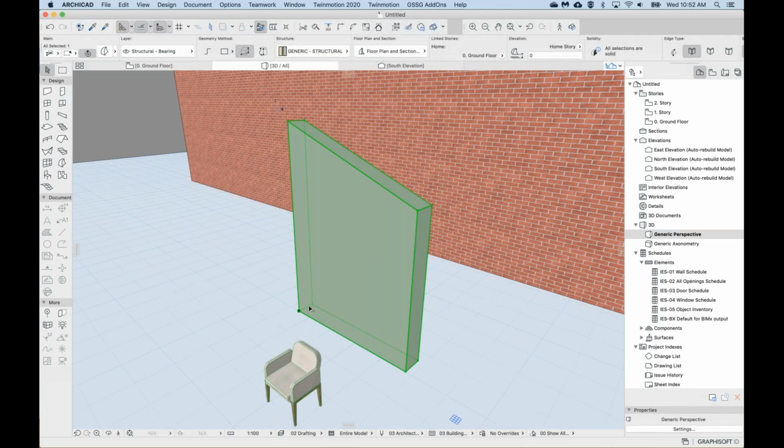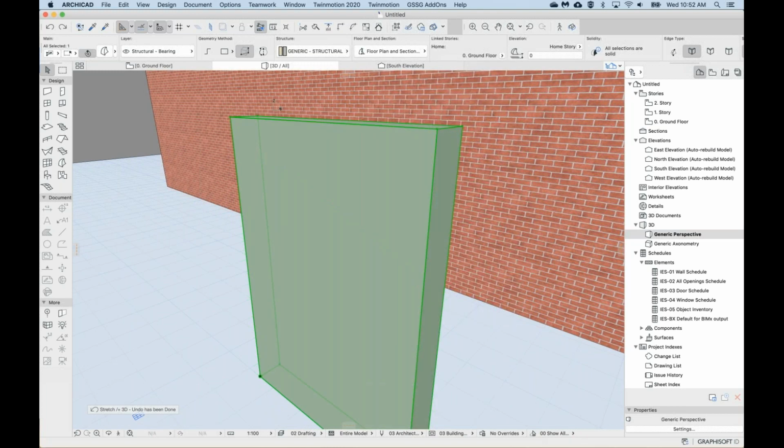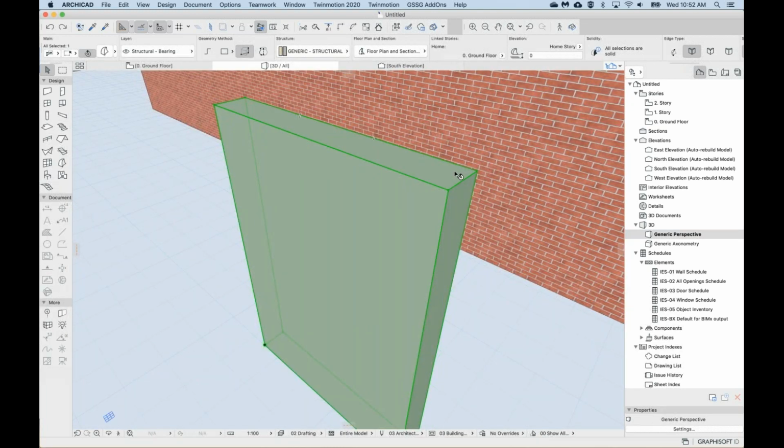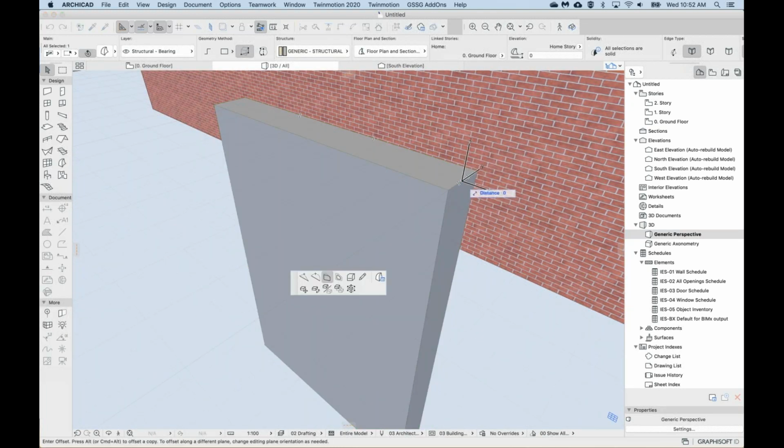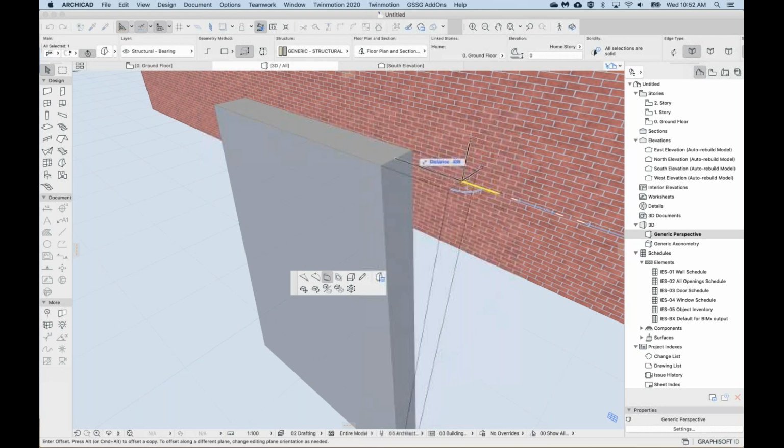So pretty much this morph is almost like a thin box with an extrusion, and then I've offset an edge. So I'll do that again. I'm going to undo. On this top edge, I've just clicked on the edge, and from the pet palette, used the offset edge. And then I've just dragged.